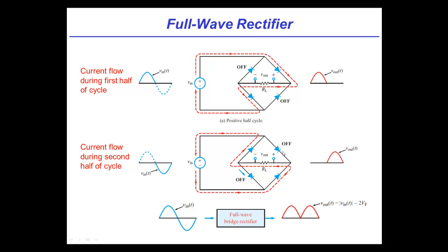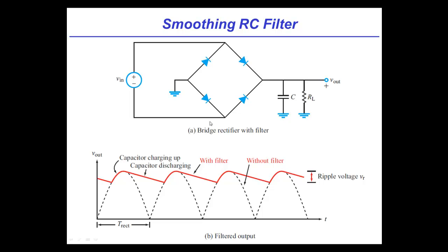The disadvantage is it takes more diodes, there's 4 instead of 2, and we have to account for the 2 voltage drops as opposed to the 1. And that's why you see that the voltage that we get is shifted by 2 voltage drops rather than by 1. Pretty cool. All right, so now we've got these little wrinkles. So we've got the output of the last stage, which is this sort of constant little half parts. It's the dashed black line, as a function of time.